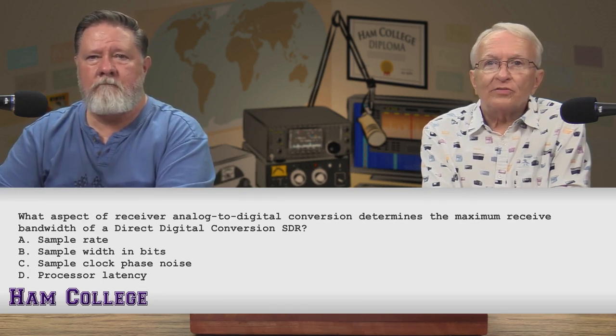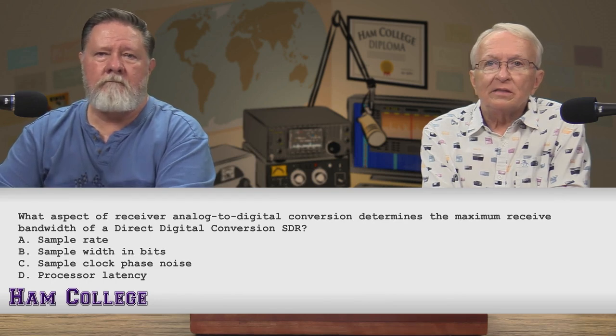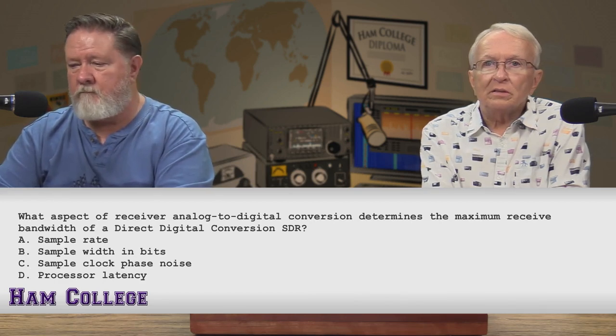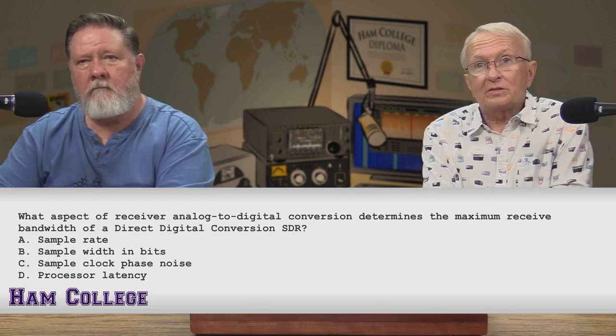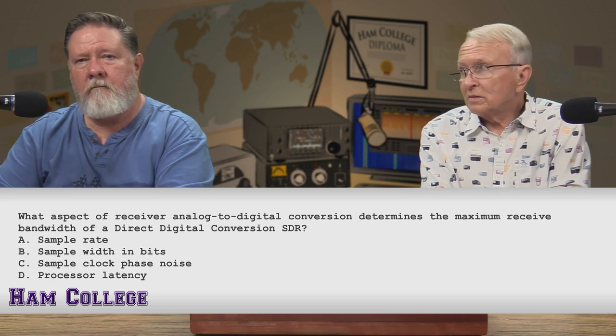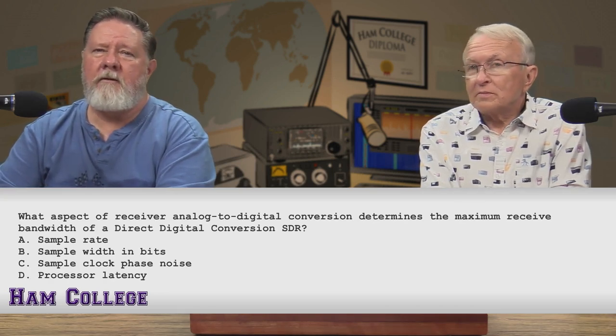It's not processor latency. It's not sample clock phase noise. It's either going to be A, the sample rate, or B, the sample width in bits. We'll just see. I'm going to say A, sample rate. What do you think? Yeah, I think so too.